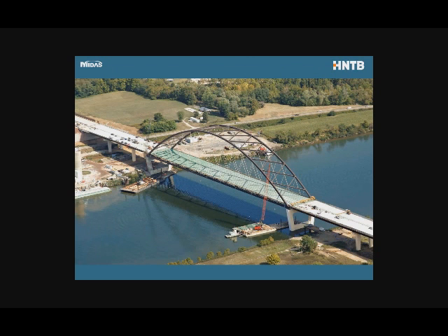For the more typical structures, this is a little bit simpler, because typically by the time you get to placing the deck, you don't need the false work anymore. This, for example, is Blennerhassett Island with the cast-in-place deck, so you can see the arches erected, the false work system has been removed, and now we'll just go and happily place the concrete deck.